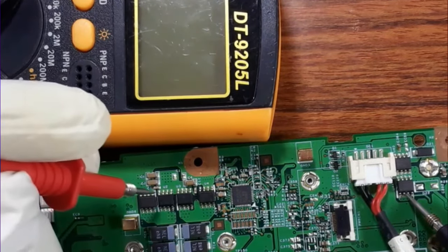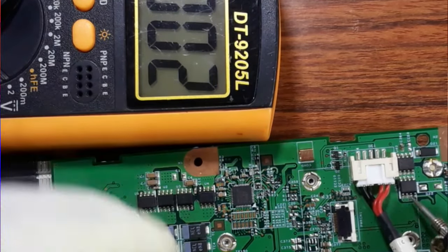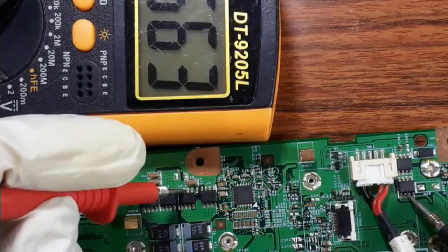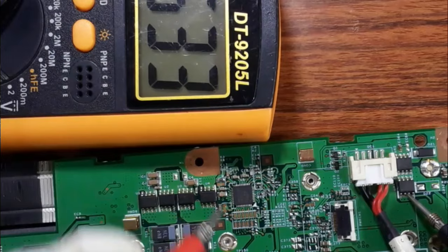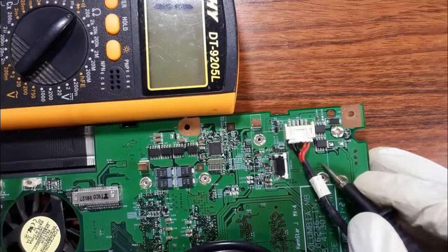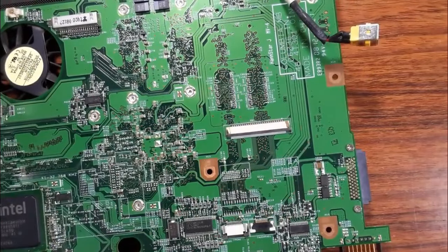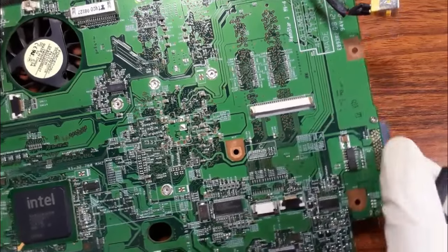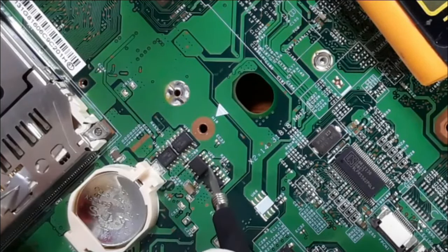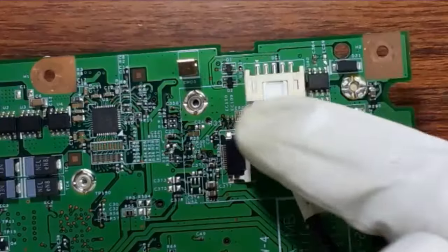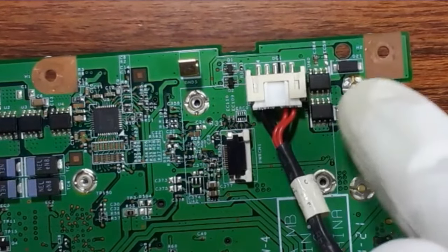Let's see another channel. Here it is also the same, as you see. Let's assume that we have 19 volts going to this MOSFET and also to this MOSFET. Also, let's look for another circuit. For example, in this motherboard, we have another circuit here. Do you see this circuit? Always, when you find a group of MOSFETs, that means this is an important circuit. As you see, we have the connector, and here we have two switches and a diode.